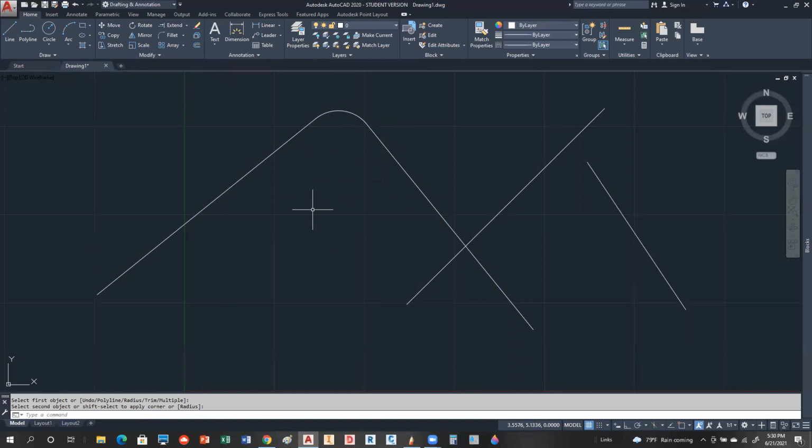Okay. So let's see how the trim and the extend work when you're using fillet. That's really cool because, again, you get like 3 commands out of 1, which is really nice. So we're going to go into fillet again, but this time notice it remembers my radius. What I'm going to do is choose radius, and I'm going to set my radius to 0.